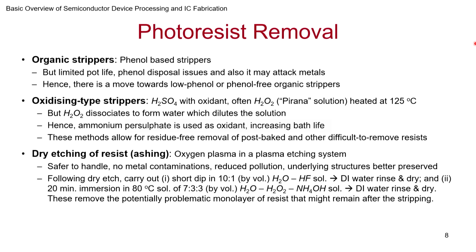So given all that, removing these can be a challenge, and these can work, but of course, as you can see, you're dealing with really potent solutions. One of the things that has become increasingly popular today is to use dry etching for the resist. You just burn it off, ash it, and at the end you do another clean. Of course, one wet etch will be there, but at least the main part of removing it, you just